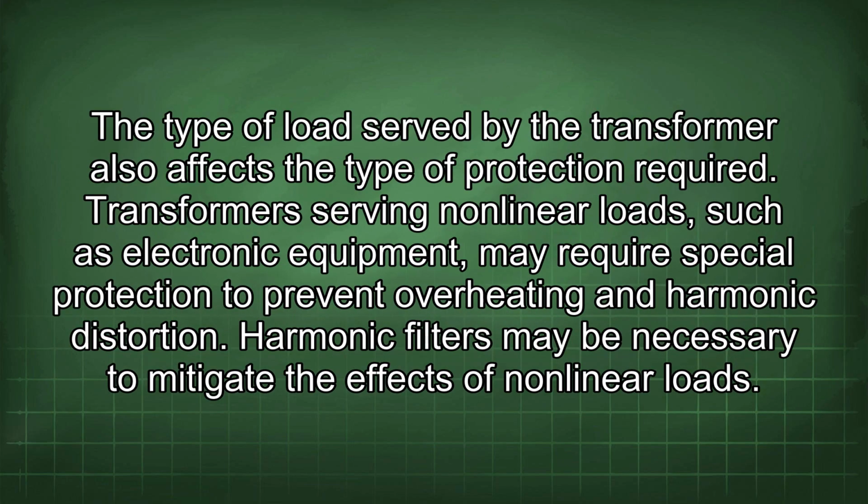The type of load served by the transformer also affects the type of protection required. Transformers serving nonlinear loads, such as electronic equipment, may require special protection to prevent overheating and harmonic distortion. Harmonic filters may be necessary to mitigate the effects of nonlinear loads.